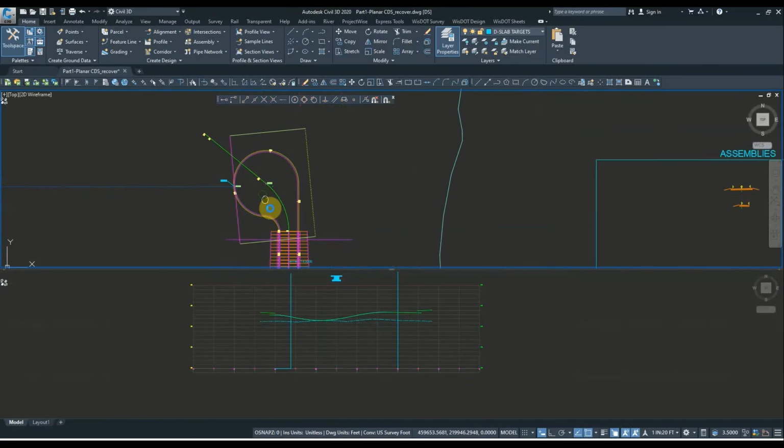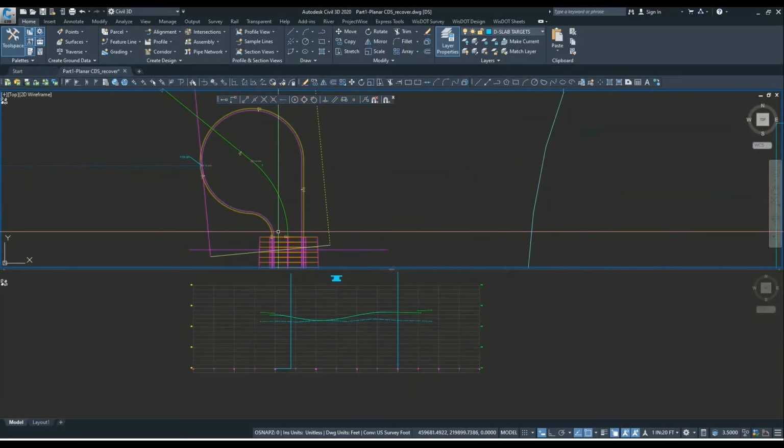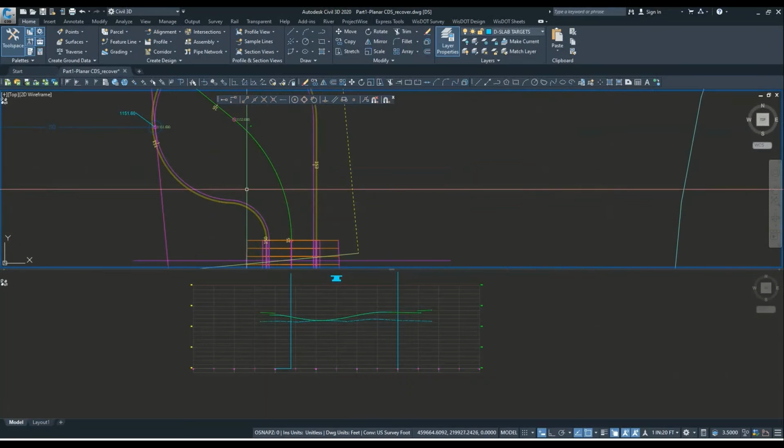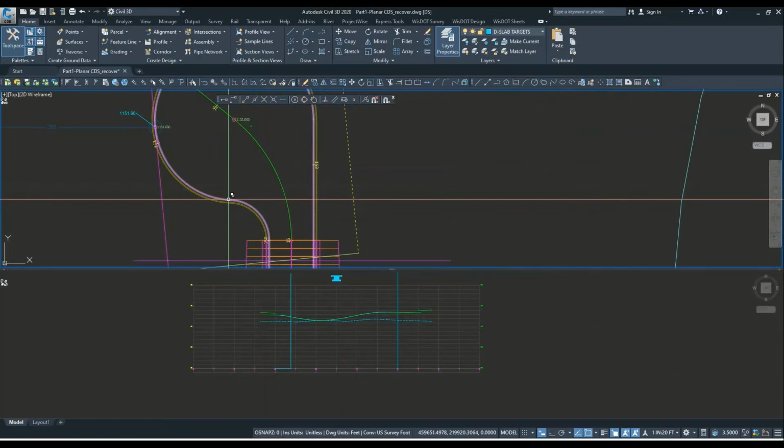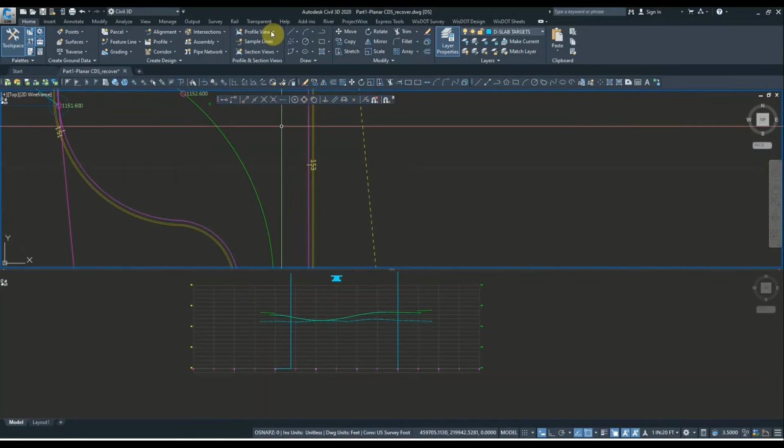So now we have what we could use as our profile for the flange, but we want to make sure that the cul-de-sac merges into what we have modeled already, and that it does so in a smooth way. So for the transition, I'll be using just this geometry point of where this curve switches locations, or sorry, directions. And then on this side, I'll just be using 153.